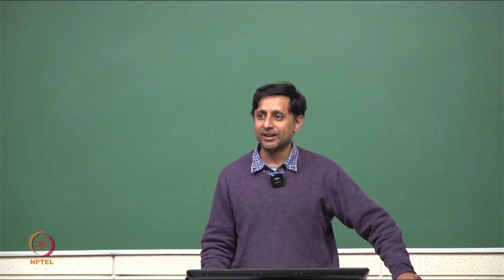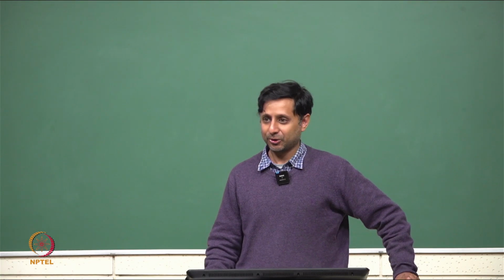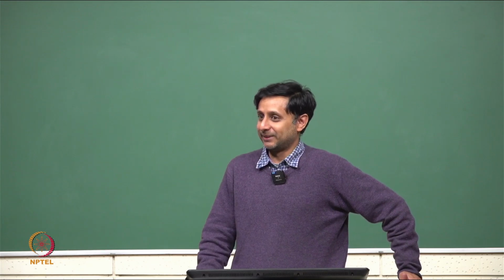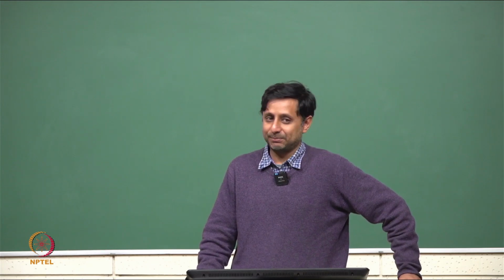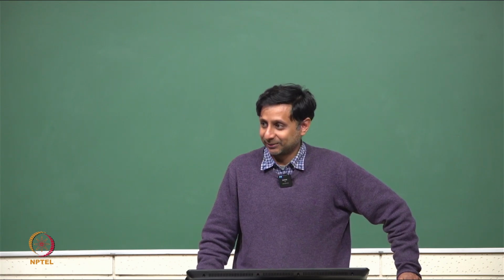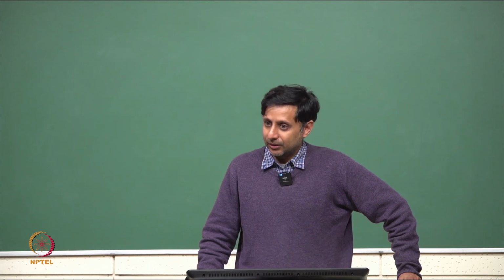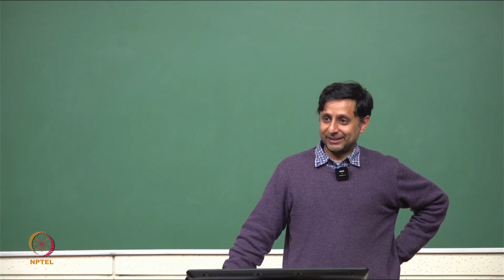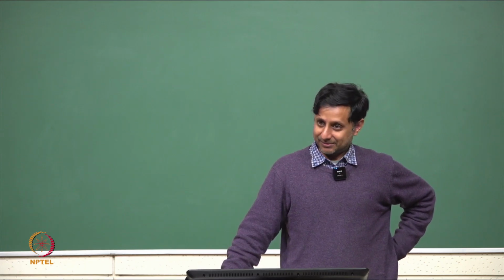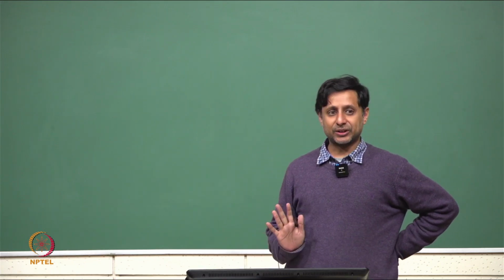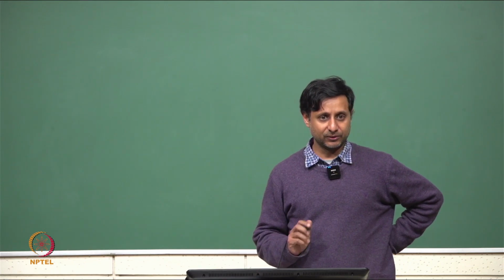In fact, I can draw infinite power from this source, there is no maximum. Okay. If Zs happens to be 0, there is no maximum, you can draw infinite power. Remember, we have done this in some class long back. Okay. So, never ask what is Zs. All right. The question is always what is ZL such that I draw maximum power from the source.